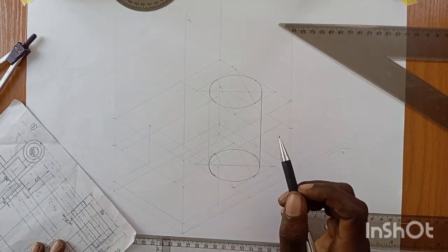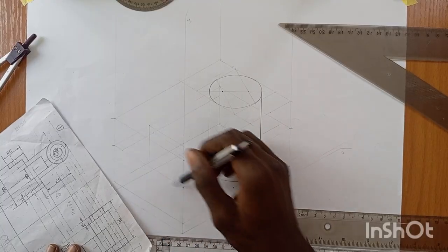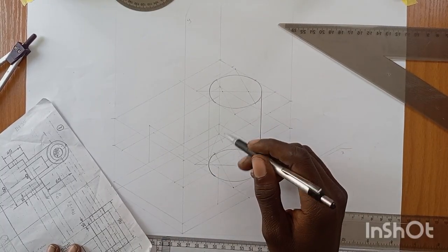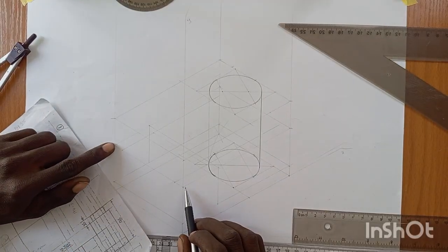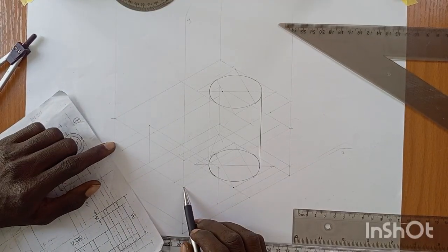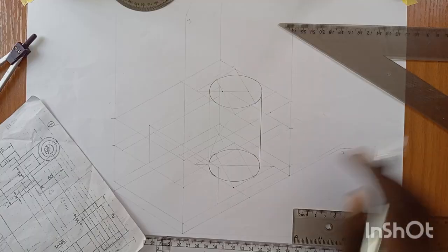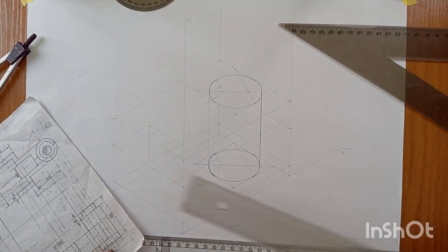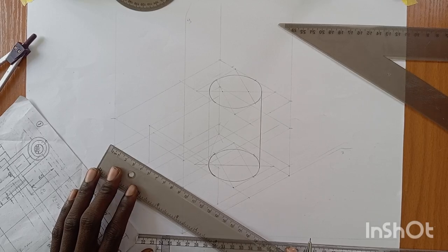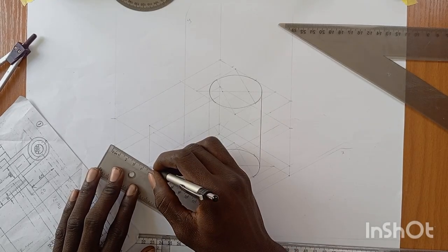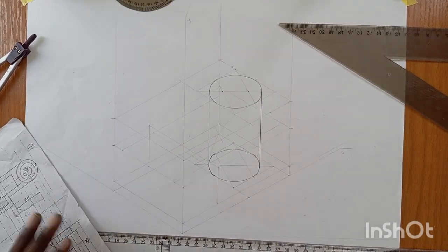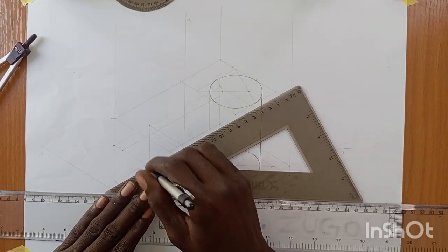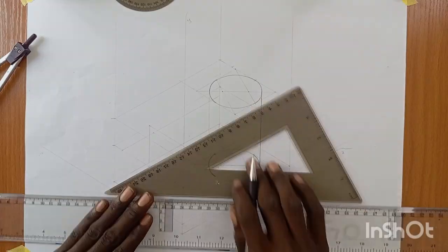So now, what are we going to do? I'm going to bisect this line into two and take 15 up and down and then push it inward. You can take from any line you wish. So this is the line we are using. Now, you can use this line also, but this one is more clearly seen outward. Let's use this one. It'll be more visible. So let's divide this into two. The width is given as 90. Then you take 45 from one side, which means you take half of it. It is bisected. Now, you use your 30-60 to push the line inward. This line inward. Okay, that's it.